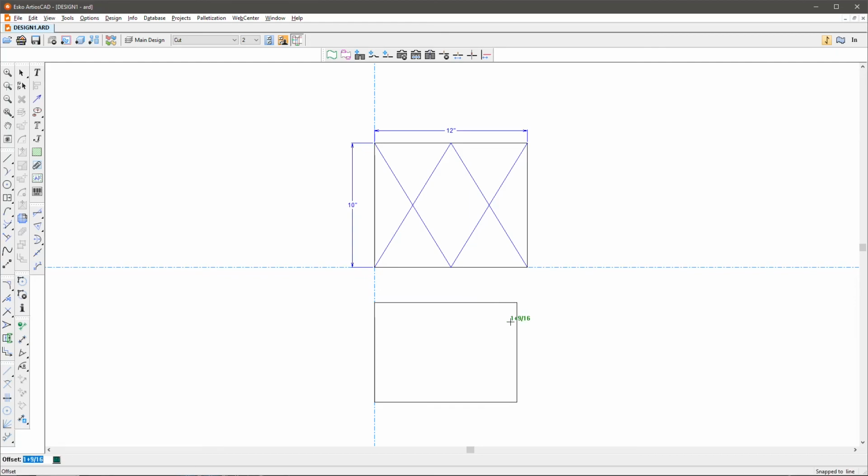So now I'm going to put the slot in. And now the way I'm going to do the slot, instead of doing a 1/4 inch slot, since this angle right here can be pretty acute, I don't want 3/16 inch board to bind up in a 1/4 inch slot. I don't ever want to bind up.